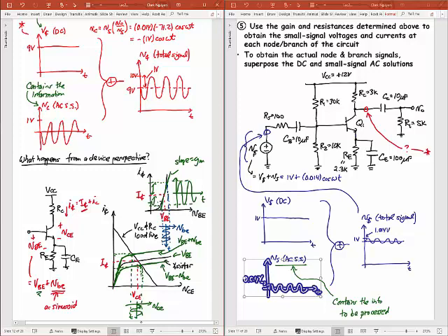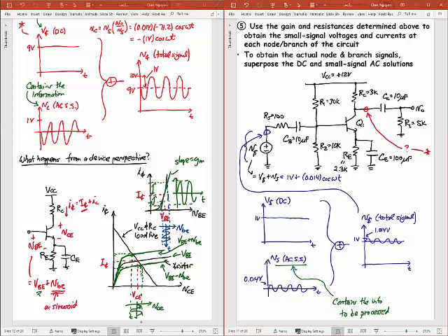Yes? So, look at the top chart. VBE changes, which changes IC. Now, the dependence on VCE changing. Is it on IC or is it dependent on VBE? It's dependent on both, basically, because I've got IC and VCE on that. It's dependent on everything. And so it's really more the VBE that's moving this thing here against a linear plot. So I will say it's dependent more on this resistor RC and that VBE. That kind of constrains the current. Yeah, so the RC keeps it very linear up here, right? Because the RC is linear, it keeps that output sort of linear.